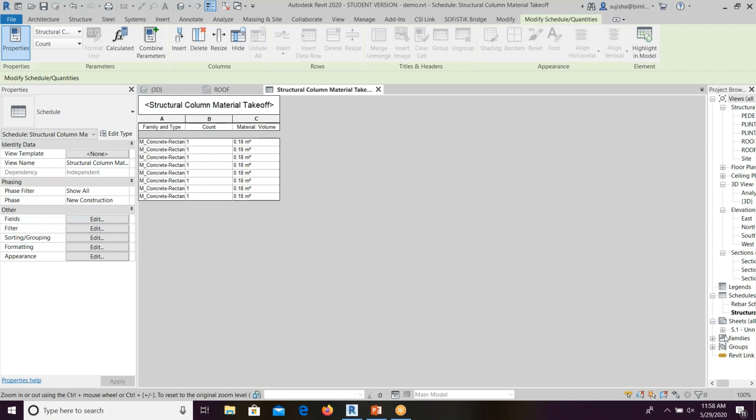The shop length of bars is 6 meters. That you have to draw individually. You have an option in rebar. While creating the rebar, you have an option called sketch rebar. With that, you have to model it individually in order to get total control of the length of the bar.